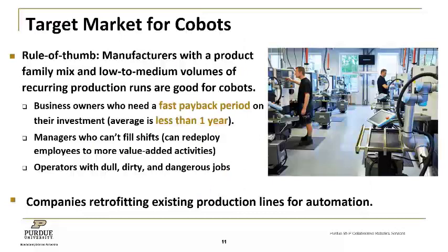So the target market for cobots. My general rule of thumb is that these cobots are really well designed for manufacturers that have a product family mix. So maybe a common product that has different configurations, different variations on it, where you have some fairly low to medium volume runs. If you've got very small volumes and thousands of different parts running through, the programming to get the cobot to handle all those thousands of different parts would probably be pretty intensive.